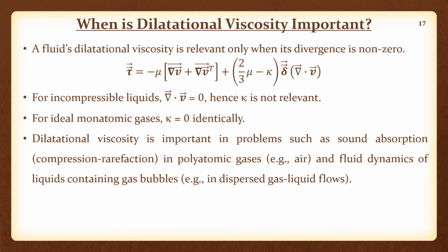So when is the dilatational viscosity important? A dilatational viscosity of a fluid is relevant only when the divergence of the velocity field of that fluid is non-zero. The del dot V term that is seen here, when this is non-zero, then this second term gets added to the first term.